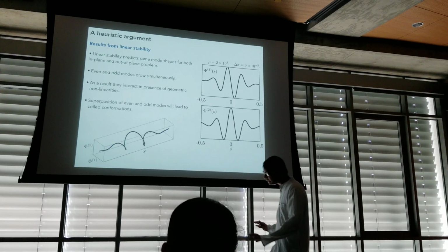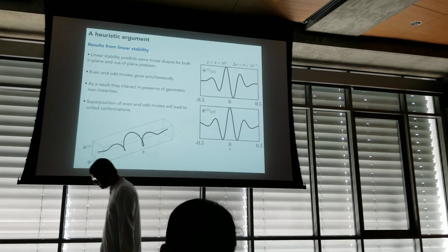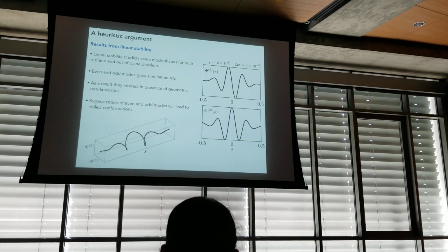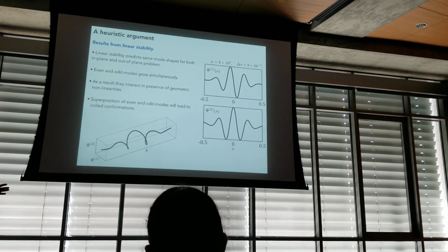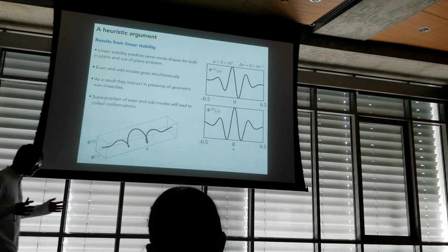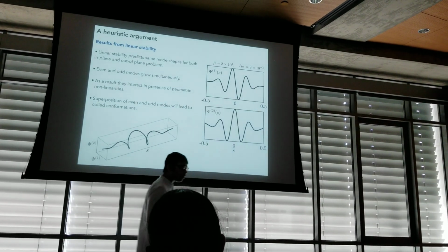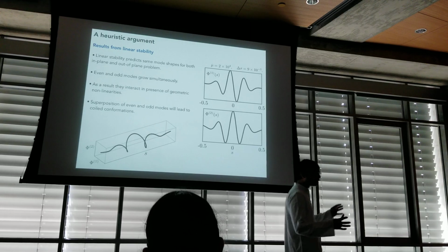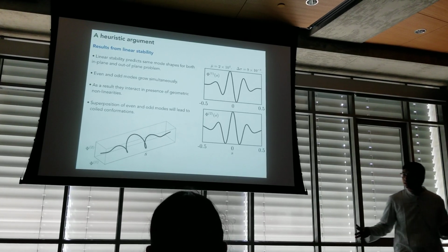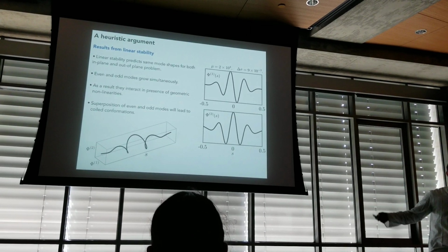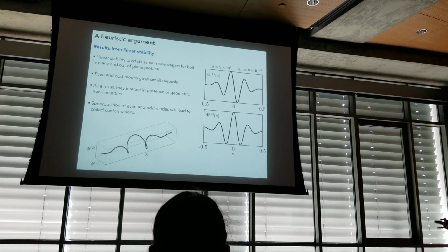These observations hint at what's going on. And this is a hand-wavy argument. Let me go through this. So essentially you have buckling, and that initiates these even and odd modes, but they have almost the same growth rate. So you cannot expect one mode to dominate over the other. As a result, these modes must interact with each other through post-buckling geometric nonlinearities.